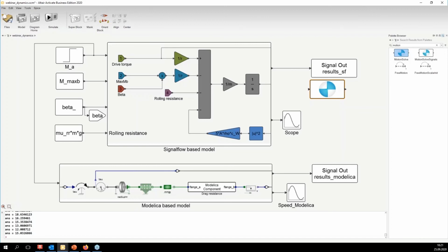Yeah, I think it probably depends a bit on your application as well. If you can linearize without too much loss of accuracy, that might make sense. But I think in model-based design, non-linearities are not as much of an issue as they would be with a full 3D model, right? If I have a HyperWorks HyperMesh composite model and I want to make it non-linear, that's a lot of effort because I need a lot of data, a lot of material, a lot of tests, and a lot of feedback from the real world back to my HyperWorks model to make it non-linear. While in system modeling, in model-based system design, it's just a matter of what sort of equation you enter, and you can directly edit the parameters of your nonlinear equation there. So you would probably need fewer parameters compared to a 3D model. Yeah, it's not a big problem with nonlinearities.